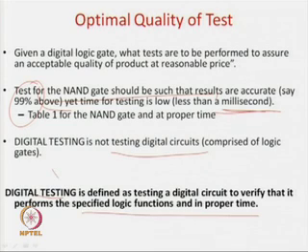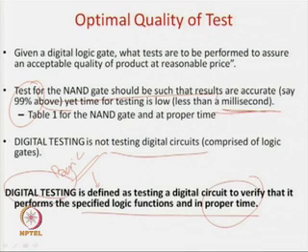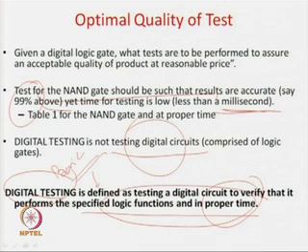This is the basic thing we should solve, because if you call it sophisticated or advanced digital testing, then it will become more complex. The very basic digital testing is that I want to know that my digital NAND gate is performing properly in the case of 00, 01, 10, 11, and it has to give me the result in proper time. If this is done, more or less my basic digital testing is over. So, it is not about testing the digital circuit entirely, which you have seen in the last few slides, but it is basically this much, a basic test. But if you want to go for advanced testing, then all these things will come into the picture.